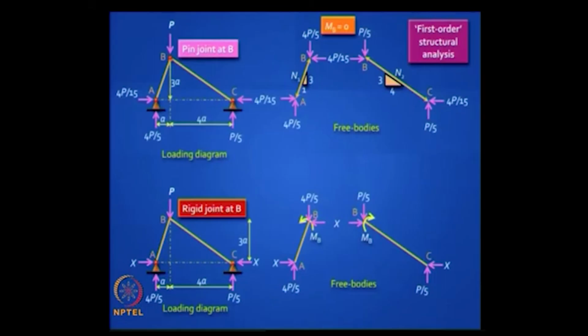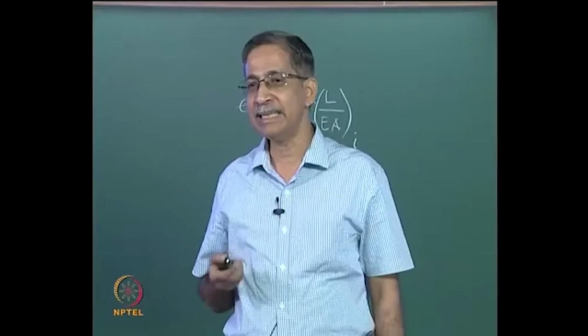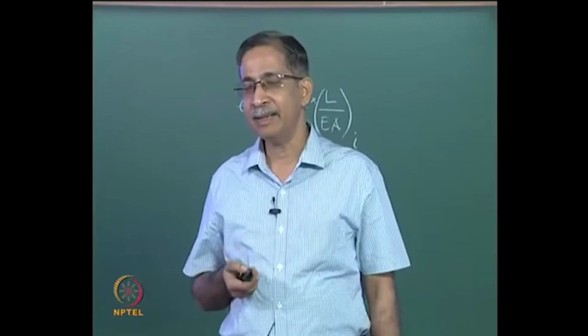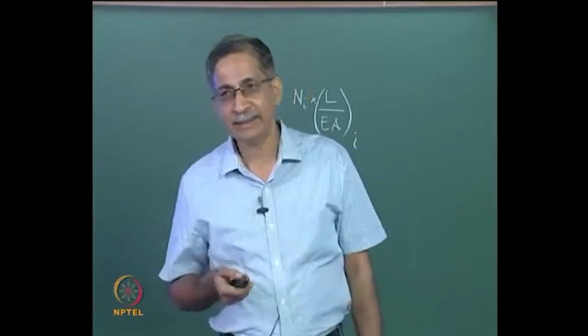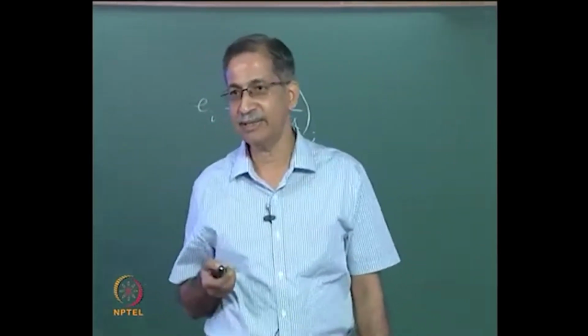Will this work? Why won't it work? No, that is not the reason. Why won't sagging moment work? Now to really understand this, try to visualize it, visualize this by looking at the deflected shape, the possible deflected shape.